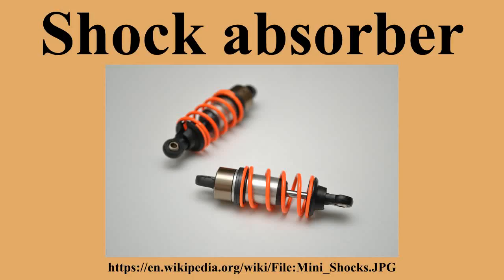Spring-based shock absorbers commonly use coil springs or leaf springs, though torsion bars are used in torsional shocks as well. Ideal springs alone, however, are not shock absorbers, as springs only store and do not dissipate or absorb energy. Vehicles typically employ both hydraulic shock absorbers and springs or torsion bars. In this combination, shock absorber refers specifically to the hydraulic piston that absorbs and dissipates vibration.